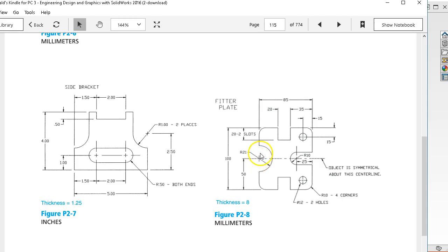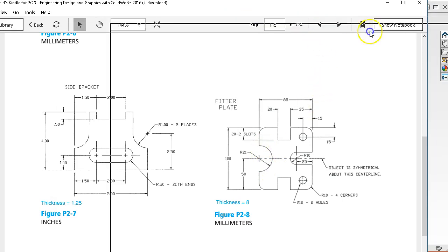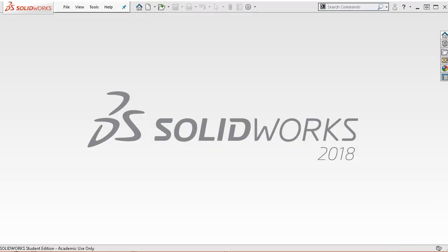And if we draw the half arcs, maybe I'll illustrate that, we need the half arc, because if I draw the full arc, it's going to mirror over on itself and create a duplicate entity, and that's usually a problem. So let's take a look at those arc segments, and then we'll build in the geometry.